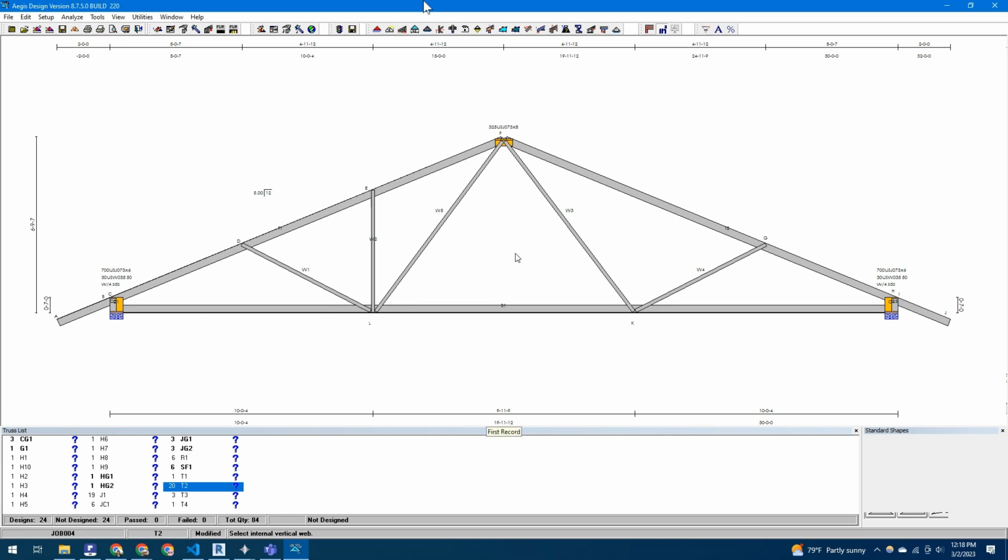Okay, that's really helpful because we had a customer who wanted this clear space on the inside of their truss for storage. And then you'd have to turn that non-habitable attic setting on to do that, to make sure that you got enough load in there.